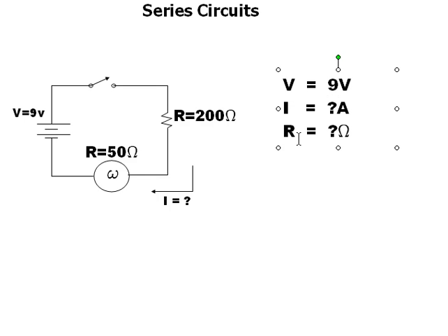The second thing we're looking for that we know or can figure out is the resistance. What is the resistance of the circuit? Well, a switch doesn't usually have any resistance, unless it's like a dimmer switch, where it's a resistor that acts like a switch. So in this case, our switch is not going to have any resistance value. But the first resistor will have a value of 200 ohms. The second thing that will resist in this circuit is the light bulb, and it will have a resistance value of 50 ohms. So sometimes you'll have items that are not resistors that provide resistance.